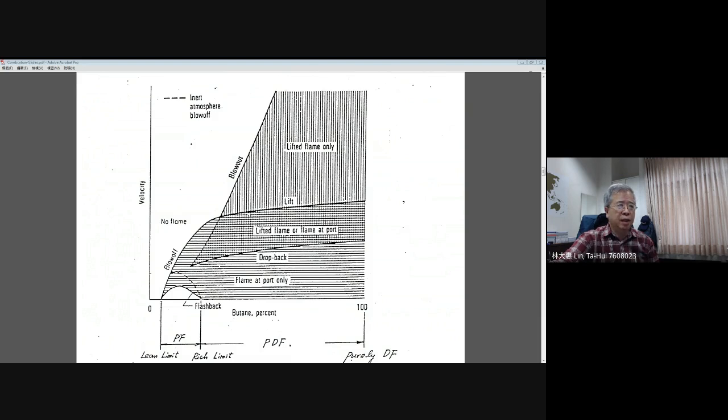Okay, I hope you understand the explanation on the stabilization of a given premixed flame, the Bunsen flame. They are bounded by the flashback boundary, and the upper bound will be blow off, depending on the injection velocity. If you have a smaller injection velocity, for a given mixing ratio your flame speed is fixed. Okay, for example, I give you an example. If the flame speed is 30 centimeters per second at this point, but the injection velocity for this point is now around 45.